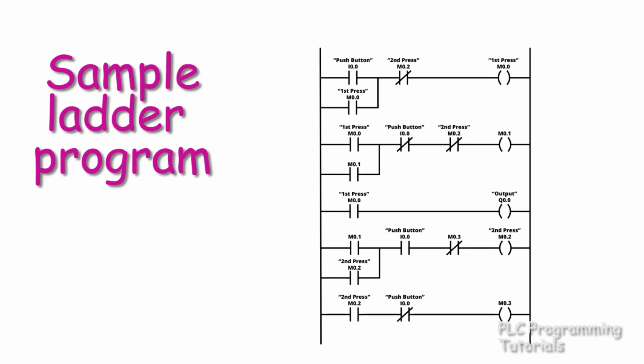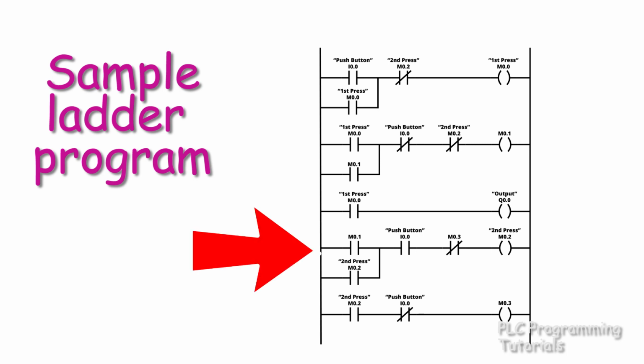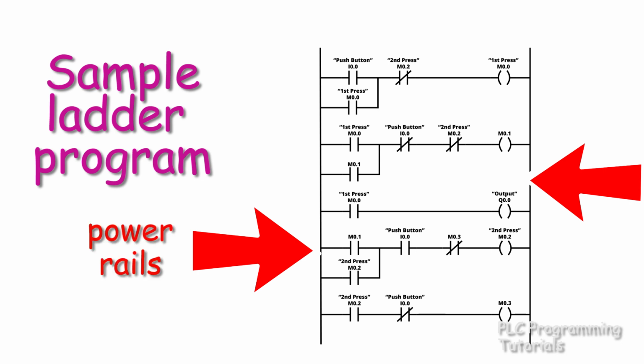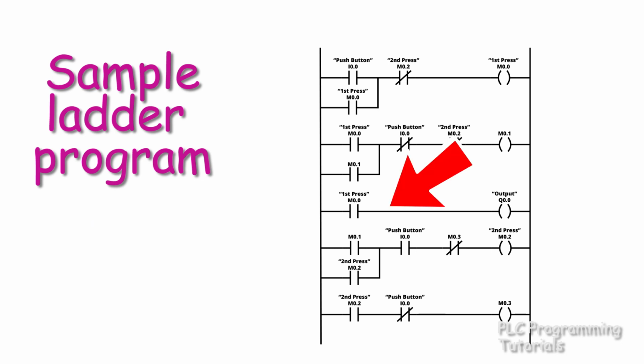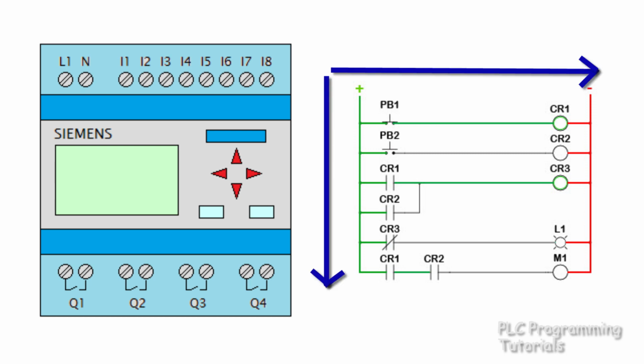It gets its name because the program looks like a ladder with different input and output relations. We can see a ladder logic in front of us. The left and the right lines correspond to the power lines. The horizontal lines where the component blocks are placed are called rungs. Once a ladder logic is written, the PLC processes the code from left to right and top to bottom.